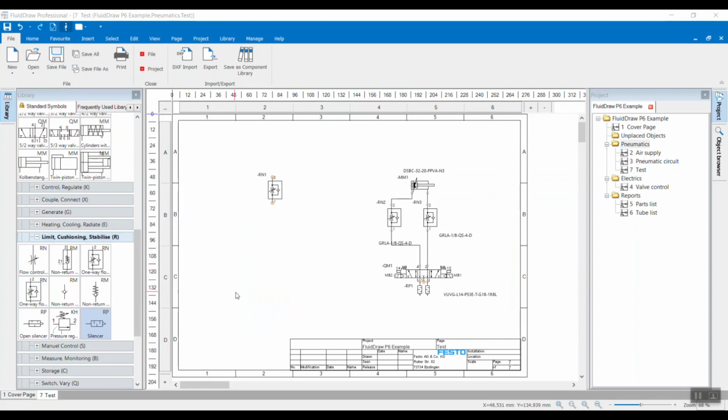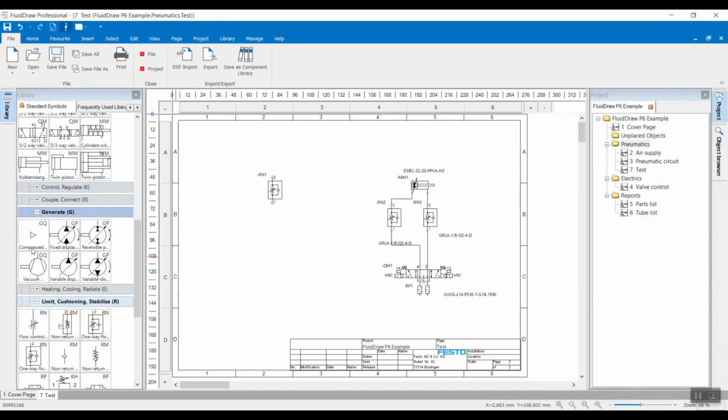So one last thing we have to do is add air to our little circuit. So here's our compressed air standard symbol. Connect it, and you saw this is easy. This is how easy it is to create a very simple pneumatic circuit and make it look very professional, except for this little text here moving around, and there we go. It's worthy of an Academy Award right now.